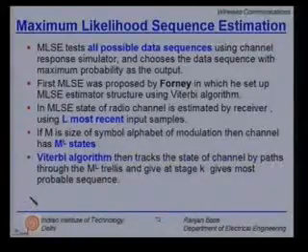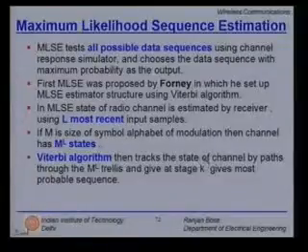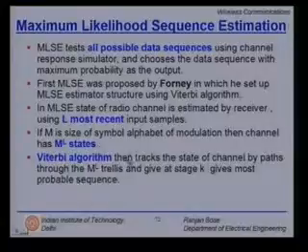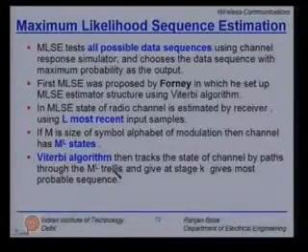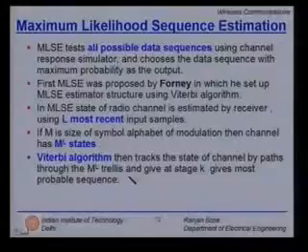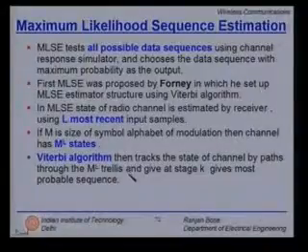The Viterbi algorithm then tracks the state of the channel by paths through the m raised to L trellis and gives at stage k the most probable sequence. So it is some kind of sequence estimation. Needless to say, it will be computationally very intensive, but you will get a much better minimum mean squared error.